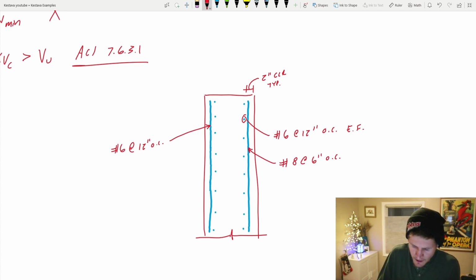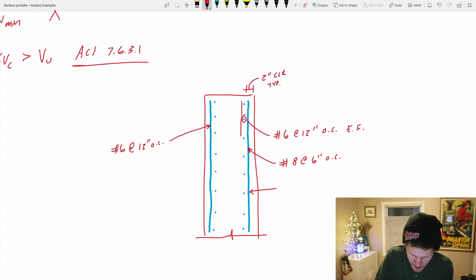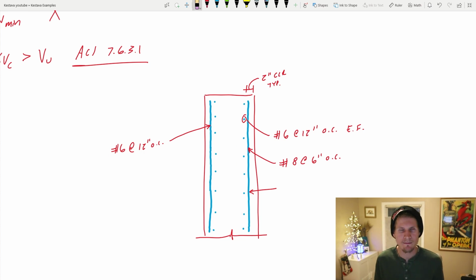And one thing we want to make note of is that your longitudinal bar, you want to be on the outside face of that mat. The closer to the edge of your concrete stem, the more capacity you're ultimately getting in your structure. If it were to be on the inside and your temperature and shrinkage reinforcement was on the outside face of that mat, it would be less efficient of a structure, just by a little tiny bit in terms of capacity. But hey, you might as well get the full strength of your design, especially when all it takes is just the order in which to construct it. So remember little things like that.